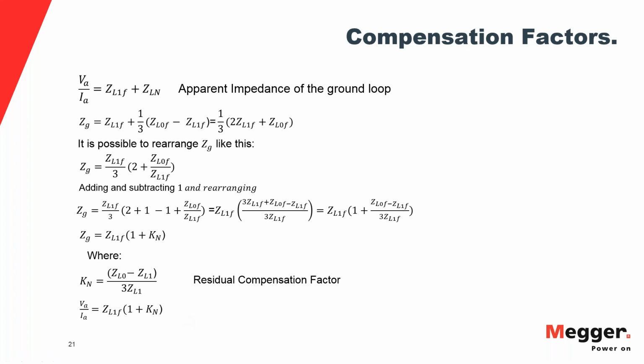Now, we did some sleight of hand here. We were using the positive sequence impedance to the fault, and then all of a sudden we came up with the absolute zero sequence impedance, and the absolute positive sequence impedance of the line. This is possible because we can take out the factor that is the fraction of the line that is represented by the fault, because it's going to be the same for the zero sequence impedance and for the positive sequence impedance. We can factor it out.